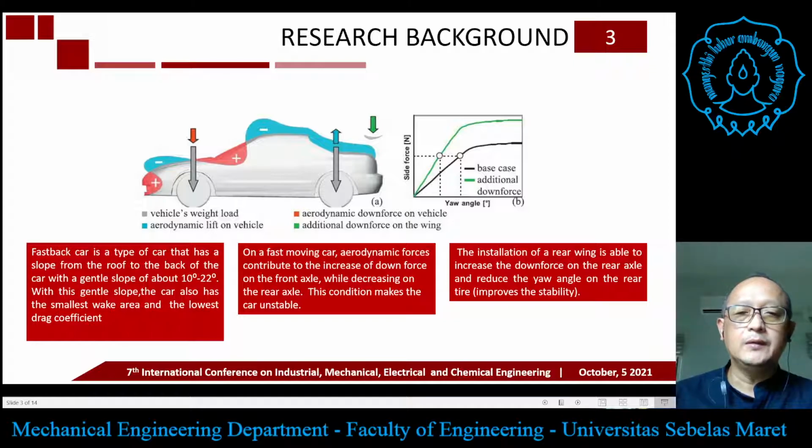To overcome this condition, the installation of a rear wing is able to increase the downforce of the rear axle and then reduce the yaw angle on the rear tire. In this case, it will improve the stability of the car.